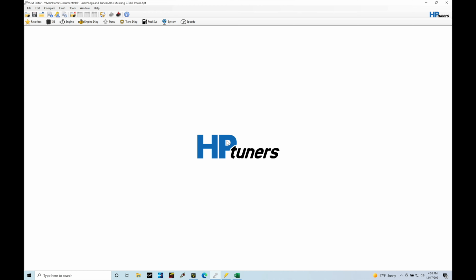Okay, so let's get started. We're going to be taking a look at the MAF calibration tuning process in this tutorial. The last tutorial we went through and checked out the basics of the mass airflow calibration curve, understanding what we needed to do in order to turn off speed density so that we were following just the mass airflow sensor, so that we were able to go into this tutorial and start to actually calibrate it using our log data from our VCM scanner. This process is pretty straightforward. We're going to check out how this is going to go from idle, part throttle, and into full throttle. So let's check this out right now.